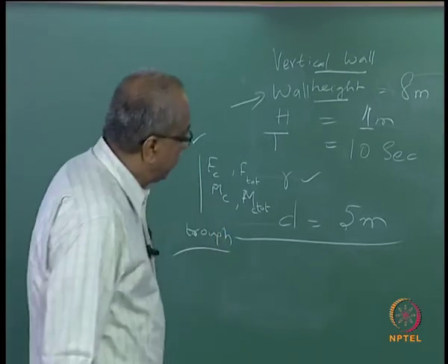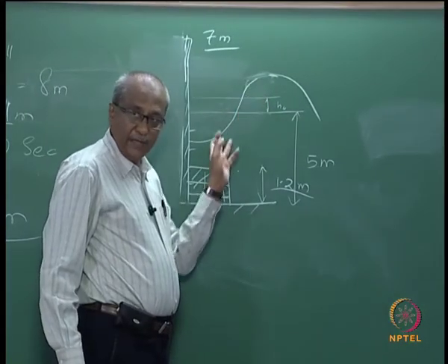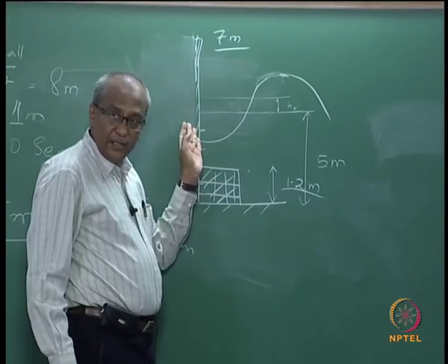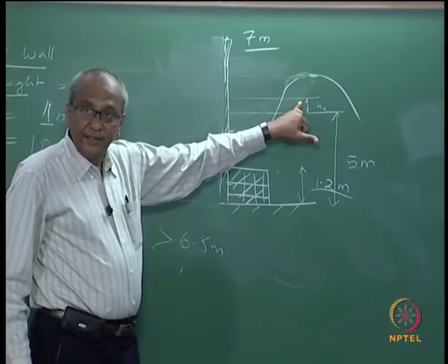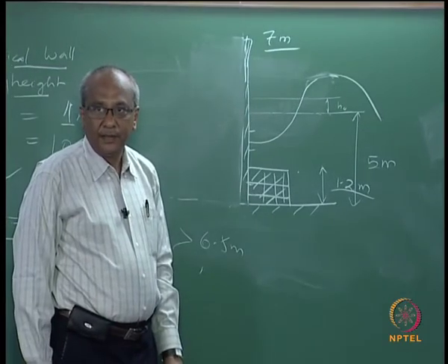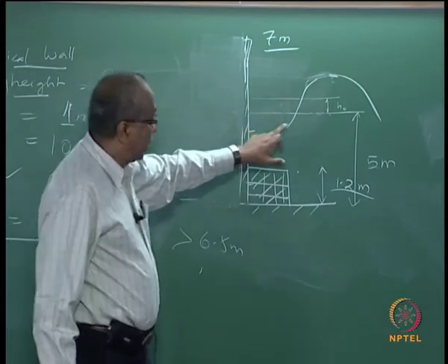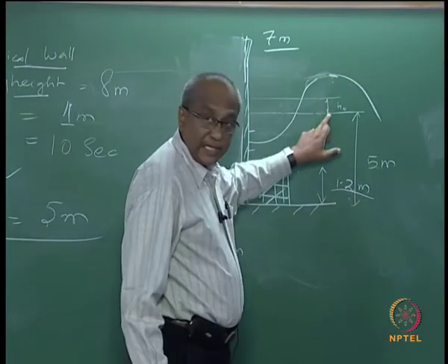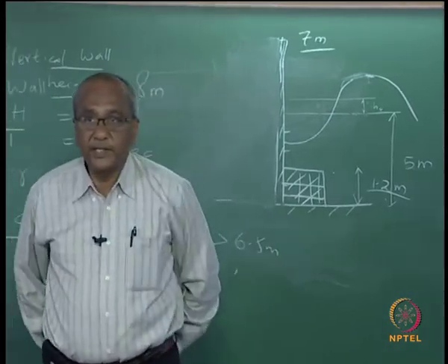Okay. Now you see that suppose a 3 meter wave height comes, it is likely to break before it reaches the wall, provided the height of the clapotis is not going to increase significantly. When you mention 3 meters wave height, that time you consider only 5 meters, but you need to also take care of H naught. How is H naught calculated?